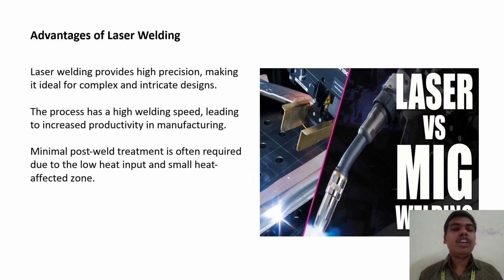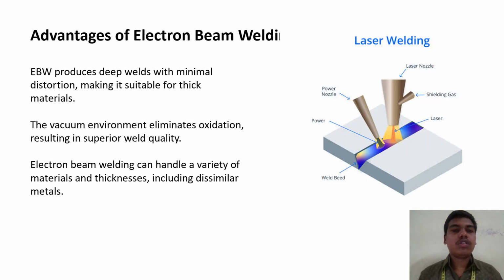Advantages of laser beam welding. Laser beam welding provides high precision, making it ideal for complex and critical designs. This process has high welding speed, leading to increased productivity in manufacturing. Minimal post-weld treatment is often needed due to the low heat input and a small heat affected zone.